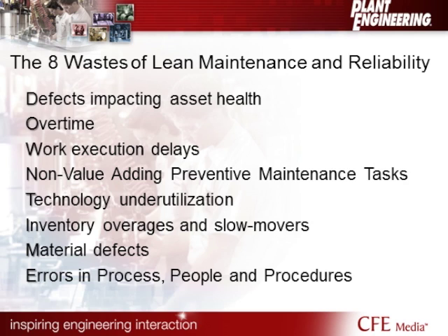The next area you see, the N in DOWNTIME, is non-value added preventive maintenance tasks. We see a lot of these. I call them pregnant PMs. These are those PMs that we keep adding tasks to over time. We've added detail, we've had a failure somewhere in the past, and someone just decided, okay, we'll replace that part on a regular interval. There's a lot of trouble with that, and I'll share more of the reasons why in just a few minutes.